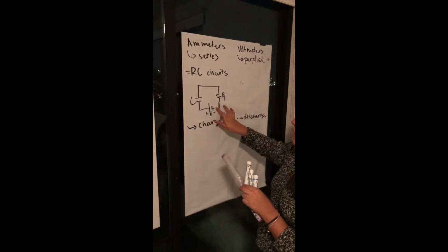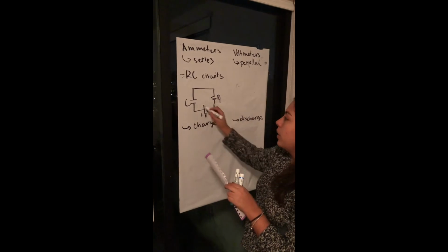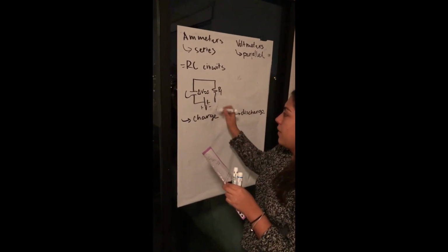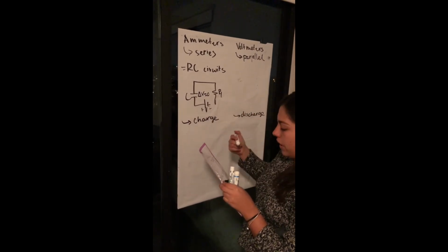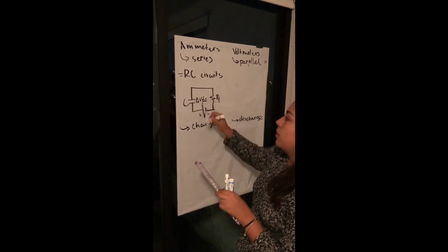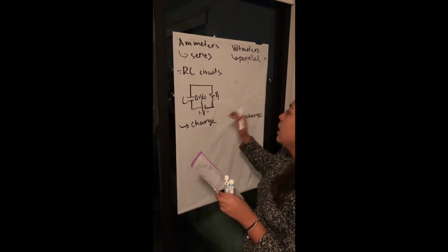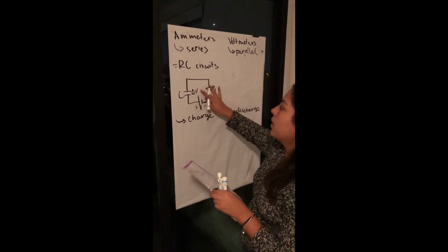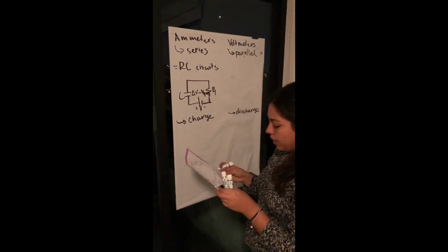We would analyze them in 3 time periods. One would be when the circuit is open, and we know that the voltage would be equal to 0 since we would have an open circuit and we wouldn't have current flowing through it. Then we would have immediately when it closes that the voltage would be different from 0, and the final analysis would be when a long enough time has passed. That would be the voltage equal to the voltage source.